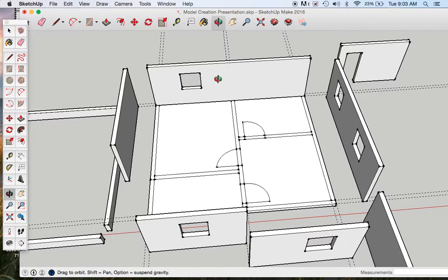I would start from the back wall, then the side walls, and the front walls. So all the exterior walls will be completed and nailed in place before you do the interior walls, because sometimes they adjust differently and it's hard to measure everything in advance and then try to put it together like a kit, because a lot of times they don't just measure up.